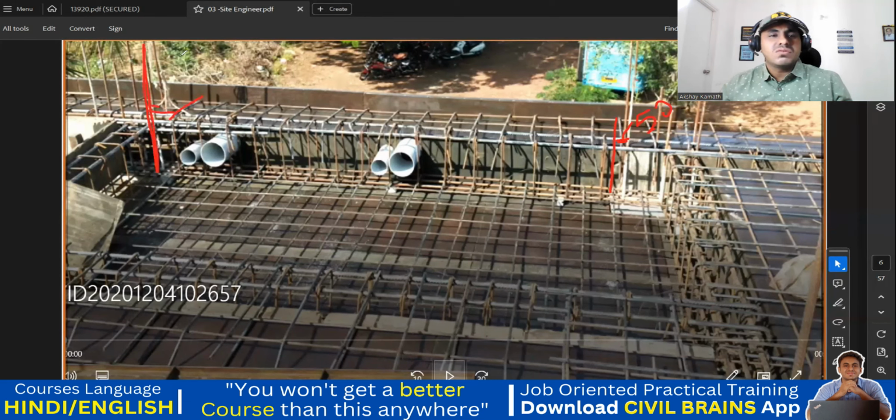So again, why is it so? Because we know that at this particular point, your shear force is maximum. So what we try to do is confine that. If you give too much gap, then due to more shear, cracks may try to propagate like this. In order to stop that, we provide a two-leg stirrup. This is leg number one, this is leg number two. Both the legs will be effective in resisting the shear cracks which will occur over there.